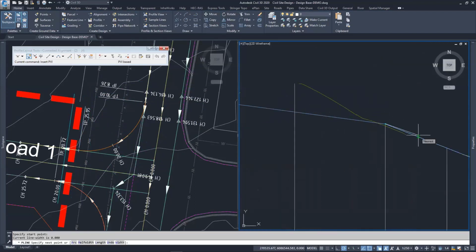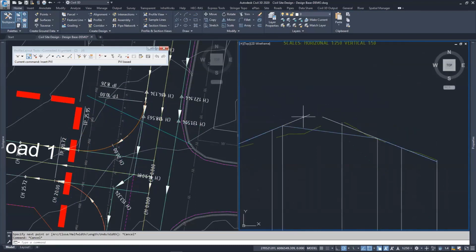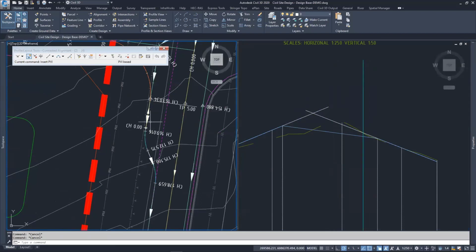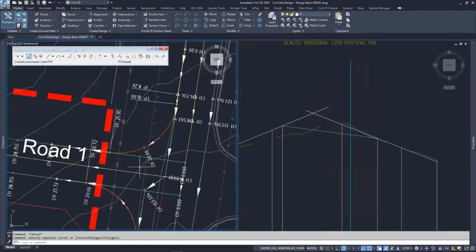I suppose it's fair to say, Terry, that designing the vertical design on top of the curve return alignment there with reverse curves is pretty much a manual process, like what you're showing, isn't it? The design of the reverse curves? Yeah. As in the vertical design for your curve return, the incoming and outgoing grades being either a single vertical curve or reverse curves.